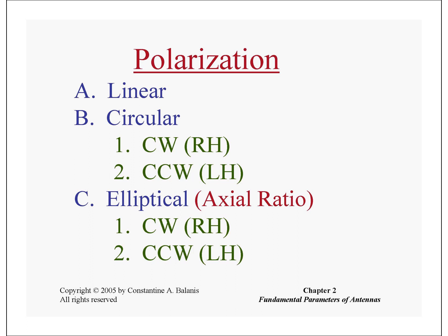Now, generally, the polarization of a wave is elliptical. However, the two special cases are linear and circular. So the ellipse can convert to a line if either of the axes is missing. Or it can be converted to a circle if the magnitude of one axis is equal to the magnitude of the orthogonal axis, that is, OA becomes equal to OB. In that case it will become circular. So generally the polarization of the wave is elliptical. However, two special cases are linear and circular.